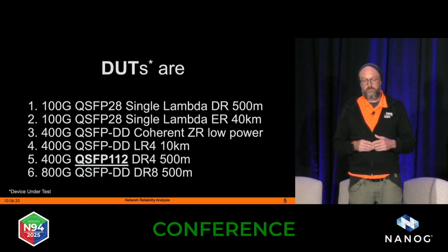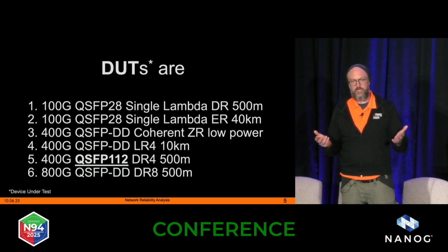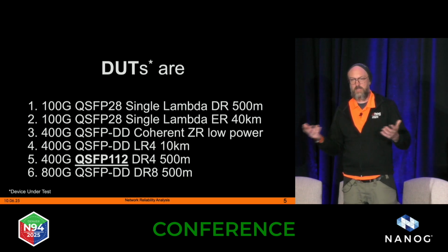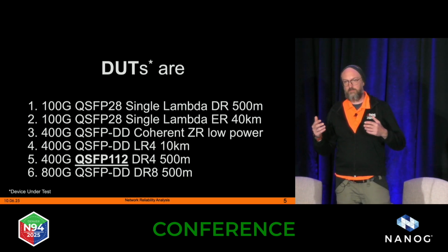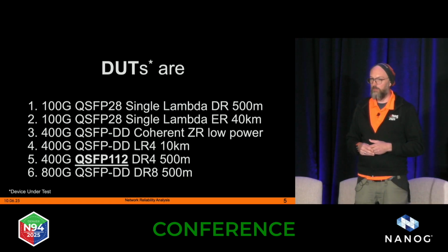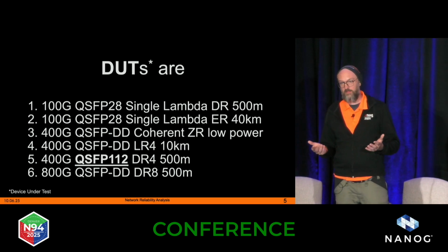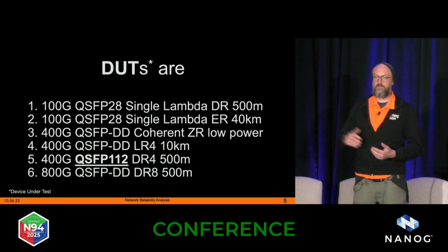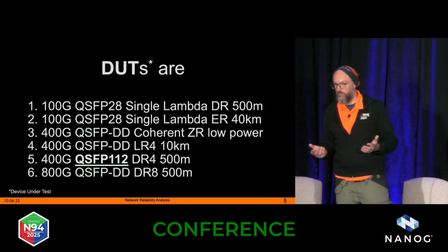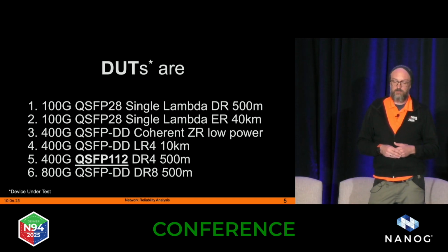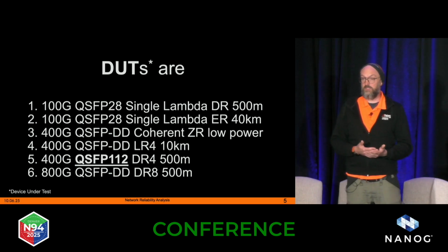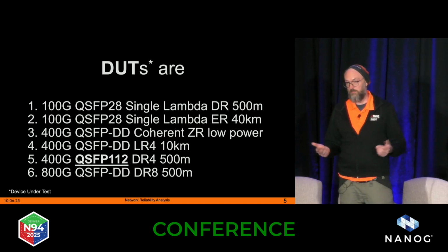Well, as a side product out of 400 gig development, the 100 gig single lambda was kind of a side product developed for 100 gigabit. So it's not 4 wavelengths on that 100 gigabit module any longer. It's just 1 wavelength. But those 100 gigabit modules do have a DSP inside as well, mainly for the purpose of the modulation scheme which we need there for the single lambda. But we also get the nice benefit that they have analysis functions inside of the DSP to run a bit error rate test, for example.